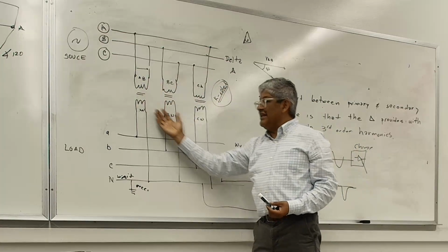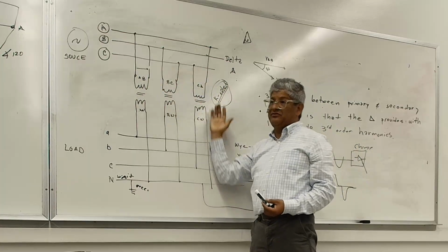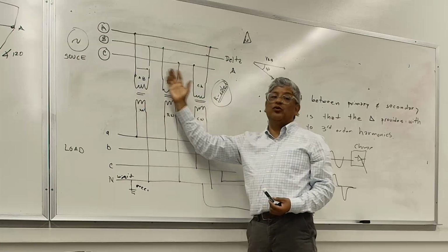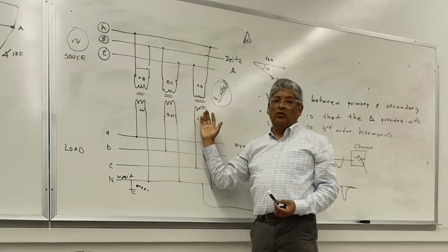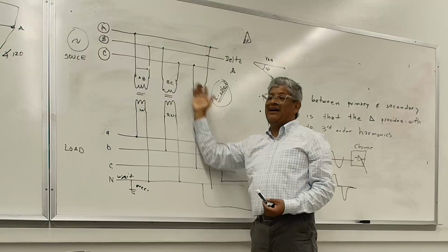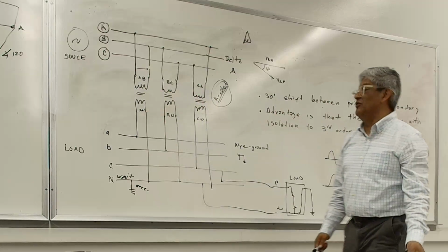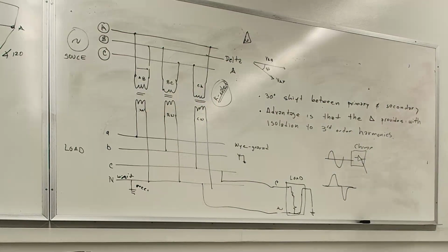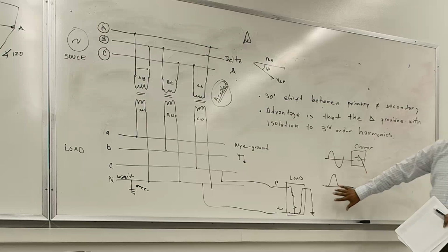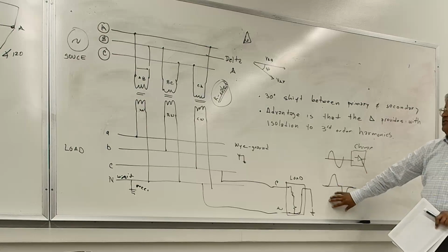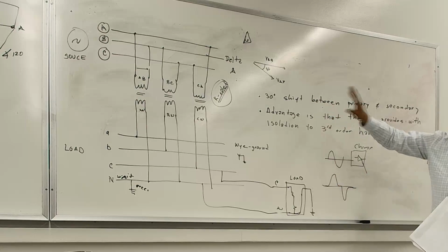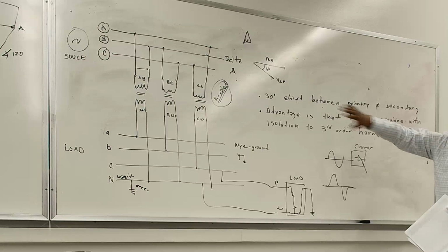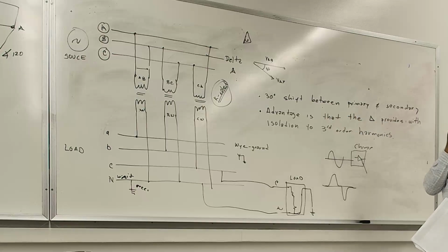So they oversize the windings and the core of the transformer to handle more power, because they're going to have to deal with higher losses because of the type of loads you're dealing with here. But again, if you want to get into more details, and if you are working in industrial systems, you'll hear that terminology. That's really what they mean.